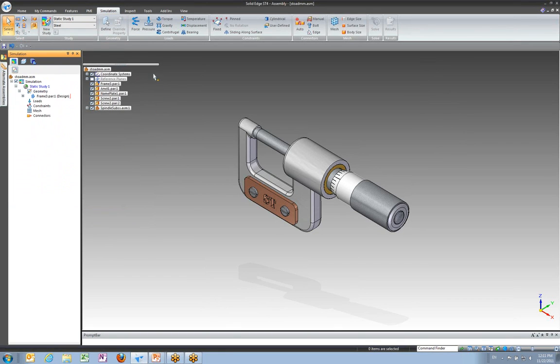And I'll talk about each of those in turn. So let's talk about loads first. That's pretty straightforward. In Solid Edge, we've got a number of conditions we can apply. The most commonly used might be stress, but we also have pressure, torque, a gravitational load, which is just, what's this thing going to do under its own weight. We even have things like a temperature load, and that would be how will this deform due to thermal expansion or compression.